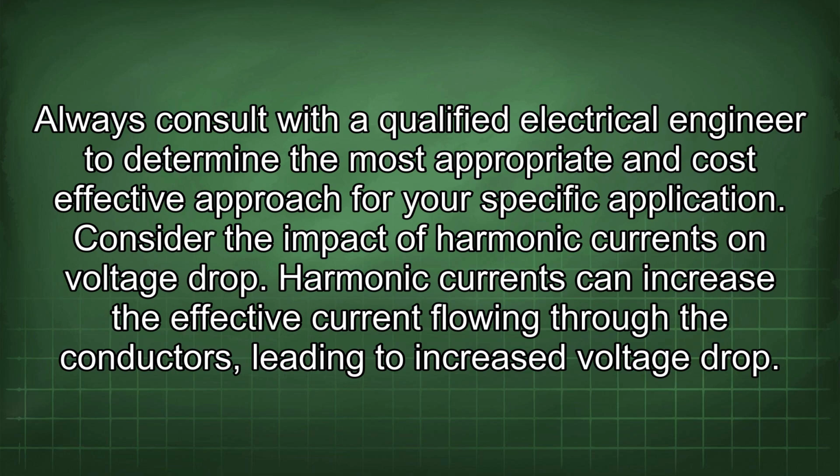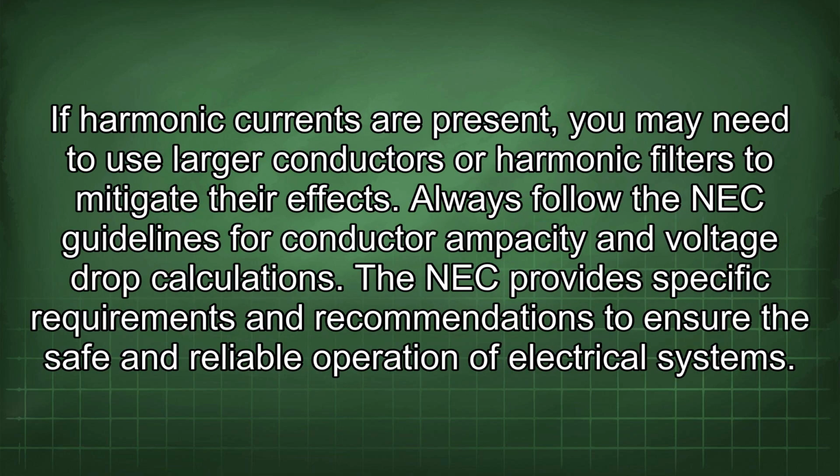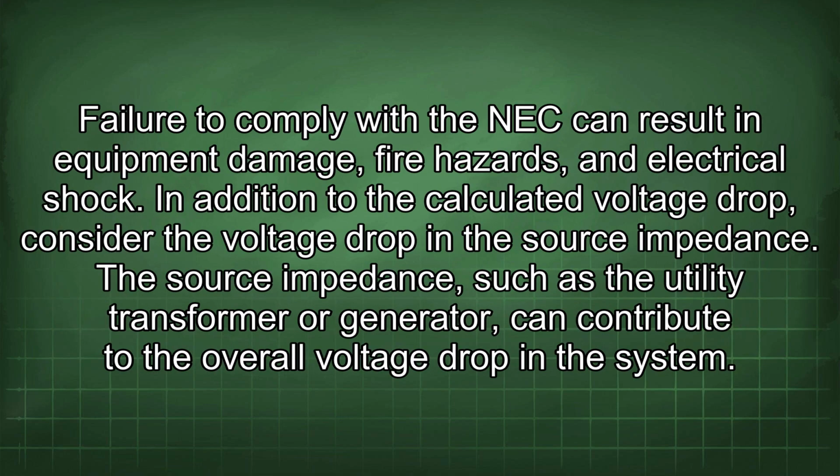Consider the impact of harmonic currents on voltage drop. Harmonic currents can increase the effective current flowing through the conductors, leading to increased voltage drop. If harmonic currents are present, you may need to use larger conductors or harmonic filters to mitigate their effects. Always follow the NEC guidelines for conductor ampacity and voltage drop calculations. The NEC provides specific requirements and recommendations to ensure the safe and reliable operation of electrical systems. Failure to comply with the NEC can result in equipment damage, fire hazards, and electrical shock.